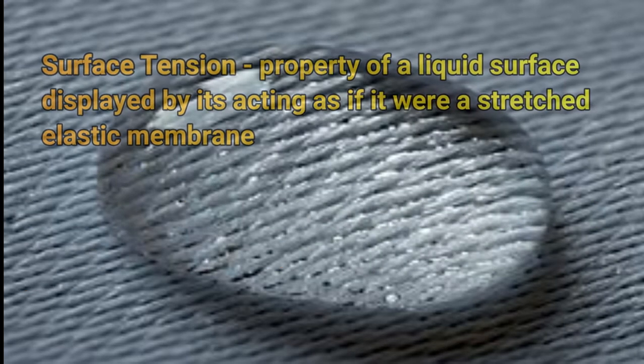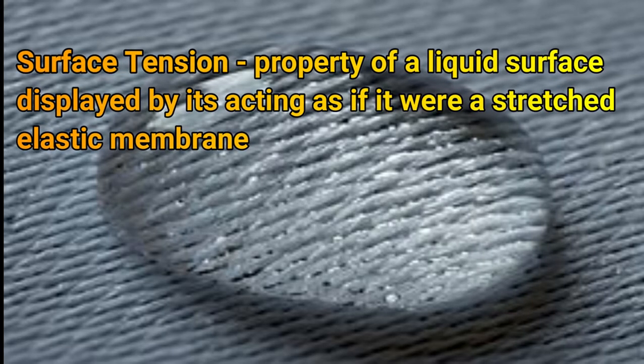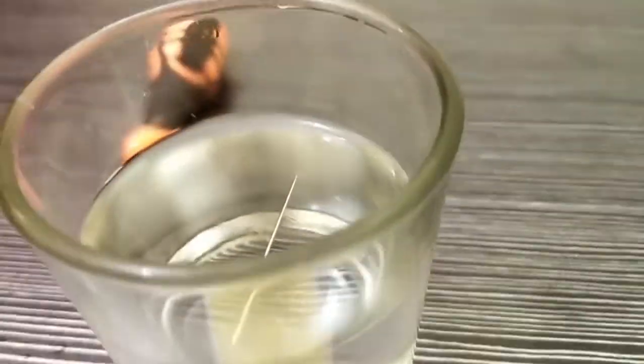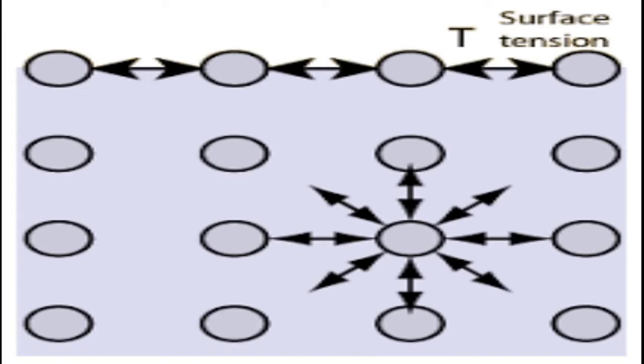Or by another definition, surface tension is the property of a liquid surface displayed by its acting as if it were a stretched elastic membrane. It is the reason why some insects and needles, even denser than water, will float on a water surface. This happens because water molecules at the surface are strongly attracted to each other, more than they are attracted to the air molecules above them. Because of this, the intermolecular force is stronger on the water surface than the bottom part of the water.